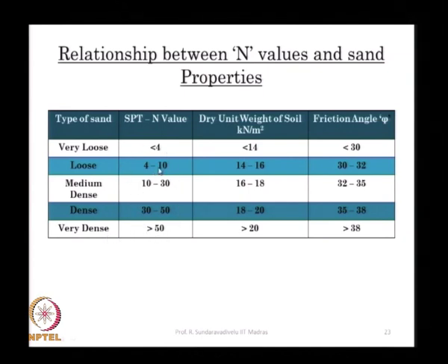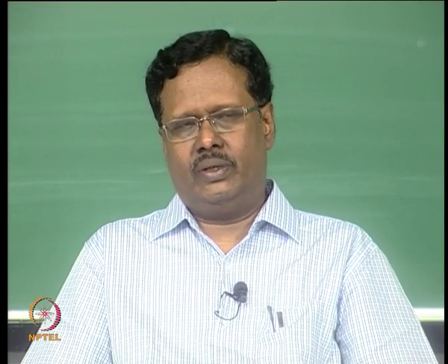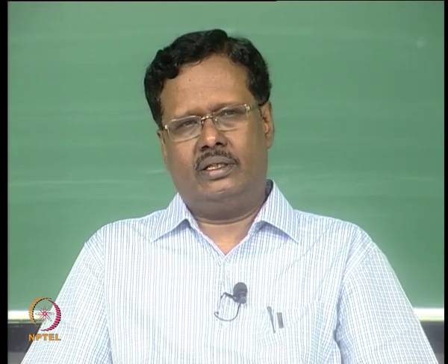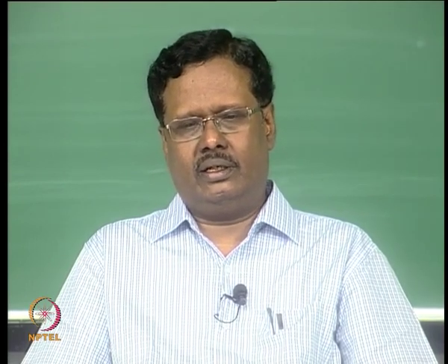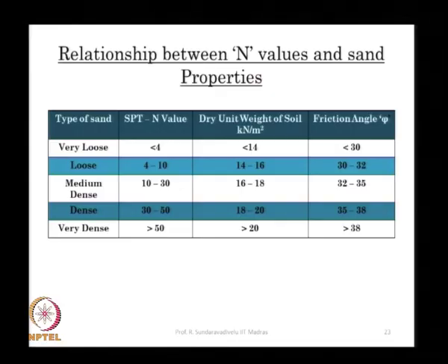As you see here, a very small N value less than 4 is very loose, 10 to 30 is medium dense, greater than 50 is very dense. Sand liquefies when you have an earthquake. SPT N value less than 10, then it is a very loose sand, then it liquefies. Then you have to do ground improvement for that.